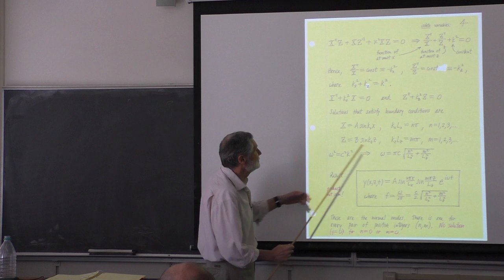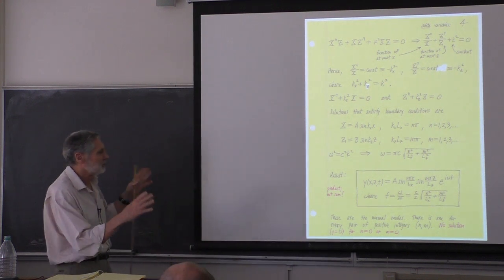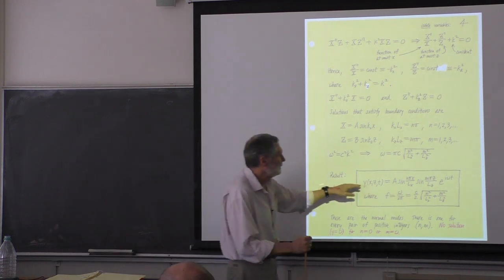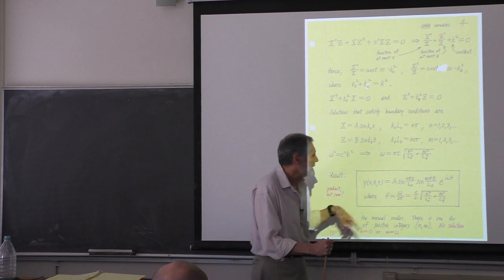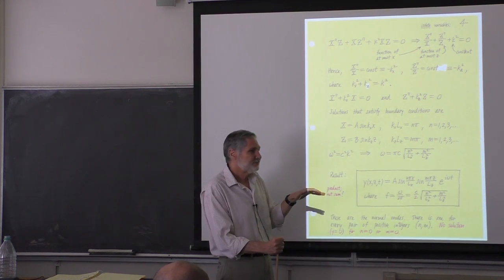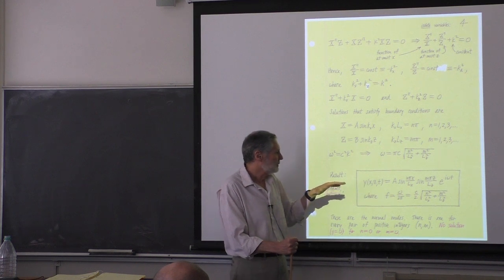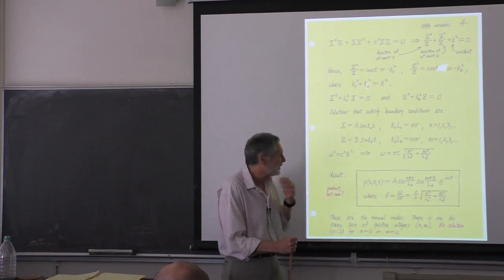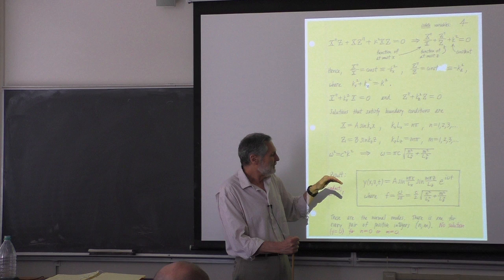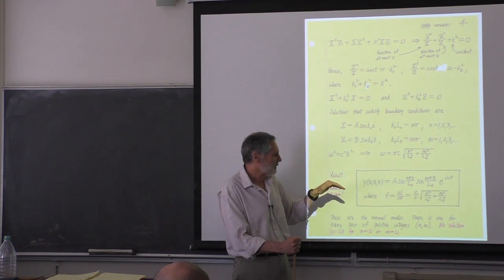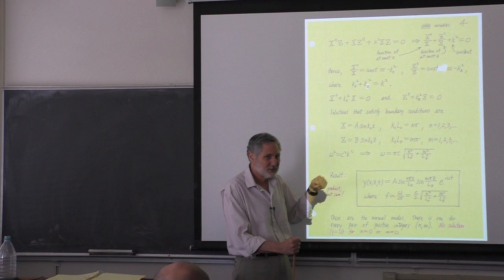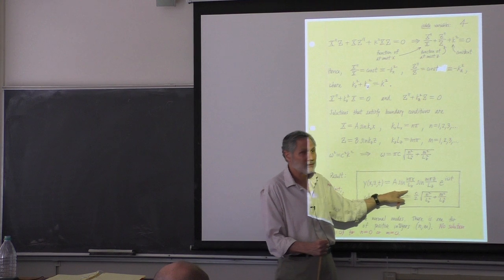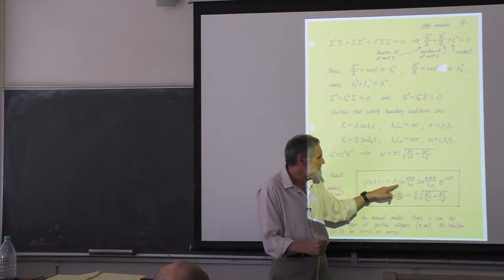So anyway, this is the solution, sort of the simplest first case where we have a rectangular membrane and it's fixed around the perimeter. Here are the waveforms, and they're sinusoids with a half integral number, I can't use the word wavelengths here. In either of the 2 directions, you have half a sinusoid, 1 sinusoid, 3 halves of a sinusoid, etc. It's just like a string, in the 2 perpendicular directions.